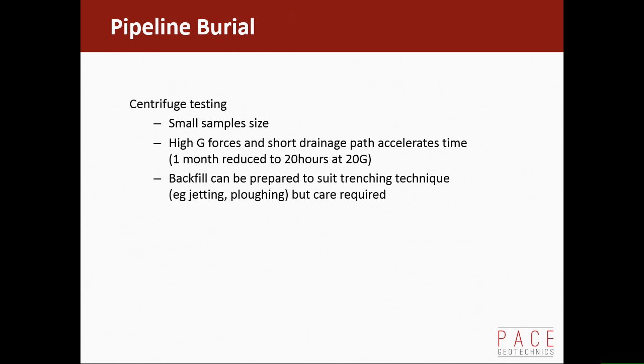The next thing is, if you've got a soft clay and you want to model the time that clay consolidates under self-weight from the trenching process, that's a function of both the in situ stresses, which are squeezing the water out, if you like, and the drainage path length, how far that water has to go before it's out above the soil. Now, if we run a centrifuge at 20G, it's like 20 times 20 in terms of time.